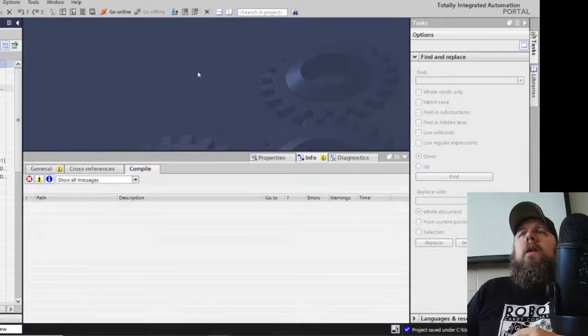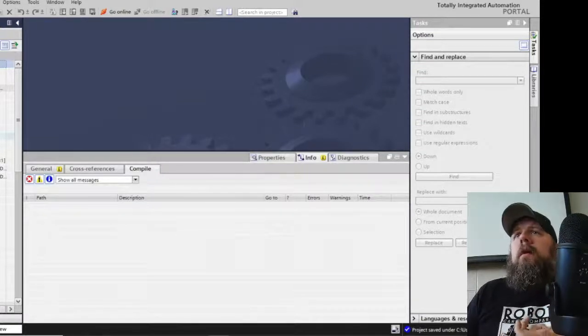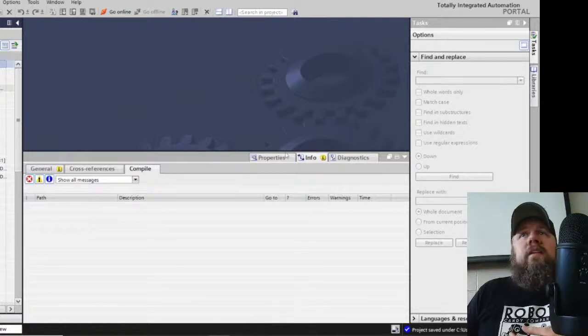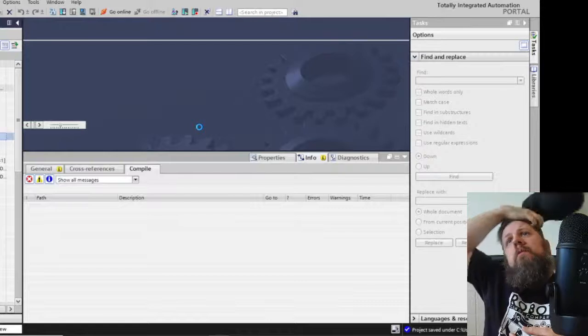The only thing I want different is I don't want people to have to code to talk to that ESP32. I want a function block that I can put out online. You pull that function block in, and that's one of the great things about function blocks: if you make a good one, you could save it and then use it in anything that you want, not just the same project that you're in. All right, so we're going to build a function block that does this analog scaling for us. Okay.